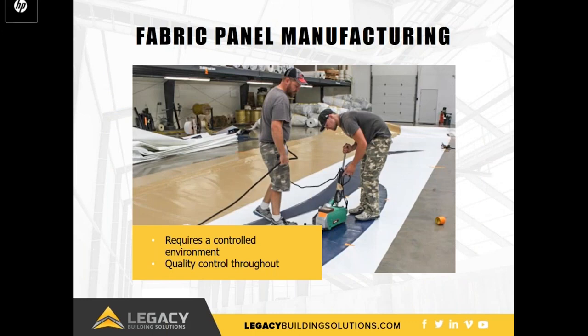Fabric panel manufacturing is the process of taking fabric from the manufacturer's roll, cutting it, and preparing it for the attachment to the frame. Before any of that begins, the fabric must be quality tested. These tests consist of visual inspection, looking for color variances, as well as mechanical testing that measures the fabric strength. Once the fabric has passed all quality inspections, panel manufacturing can begin.